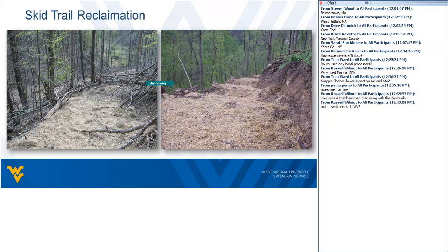Now, the main idea here is that we want to manage water off of our logging sites in as small quantities as possible, and when it's not moving with any speed at all. So low velocities, low volumes. When you have that situation, you have very little opportunity for the soils to be removed from that particular site.